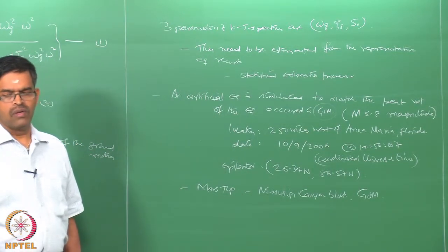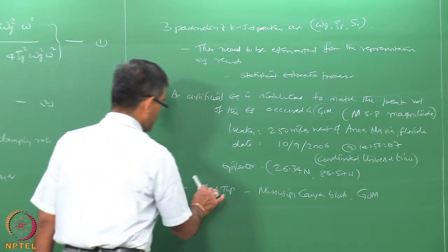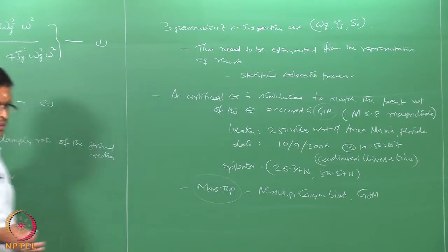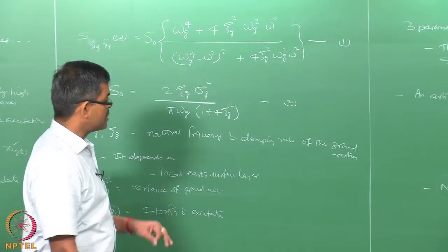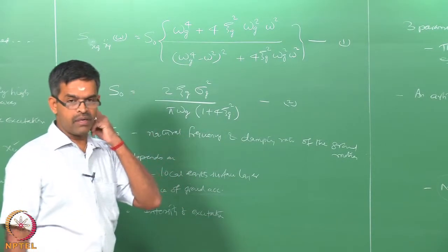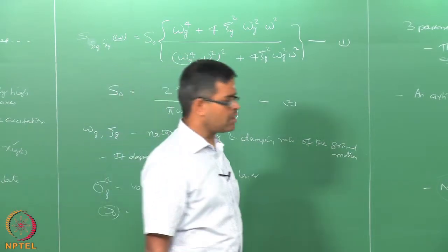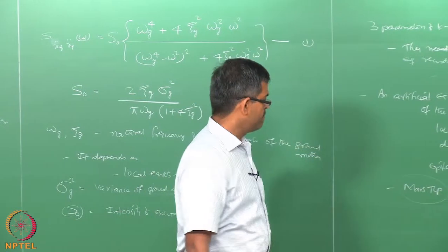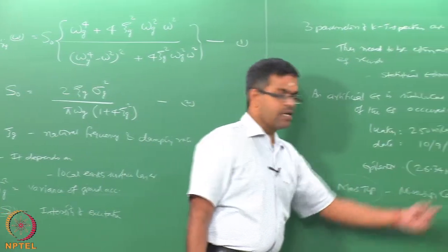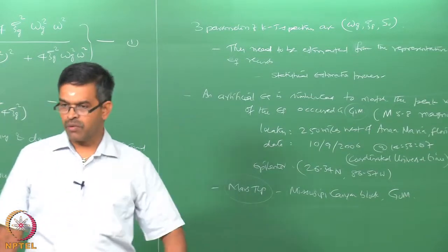So, the example was just to study what would be the safety issue related to this TLP, or a similar TLP of this order, when subjected to a combination of hydrodynamic loads arising from distinctly high sea waves and earthquake signals. One can ask me a question, how is this practical, that a TLP already existing and located will be subjected to such a distinctly higher order combination. That is about reliability.